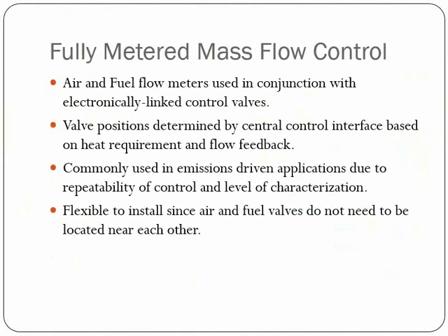And so the air-fuel ratio control system needs to see those and be able to respond to those to maintain the low NOx or low CO requirements for that system. And again, just like our parallel positioning, these are also flexible to install since the air and fuel valves and the flow meters are all electronically linked. They don't physically need to be located by each other.